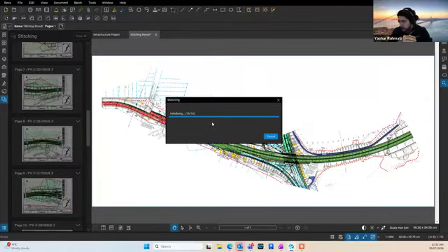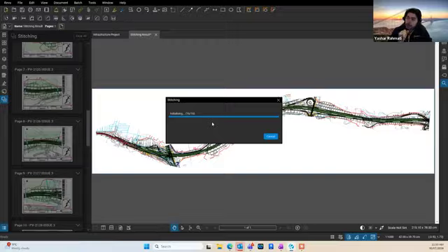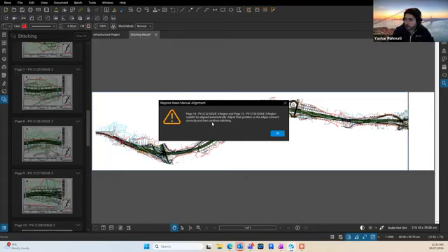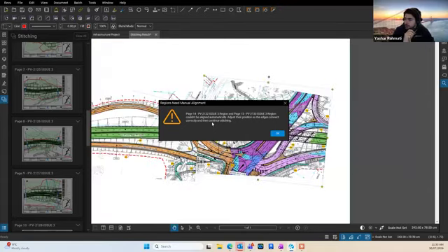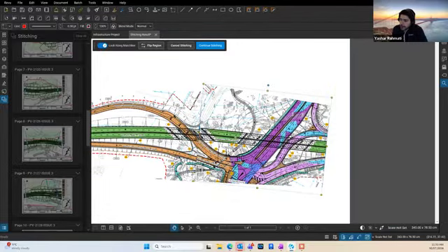Something which is a challenge is that we may not have very well aligned stitch lines, or sometimes the software may just find that there are some discrepancies. But the great point of this feature is that it doesn't stop. If I've got some regions where the match lines are not aligned, we get an error, exactly as you can see here, and we have time to align it ourselves manually. We can position it a bit further into the position, and then we can continue stitching. So it doesn't get interrupted by having stitch lines not in the right position.